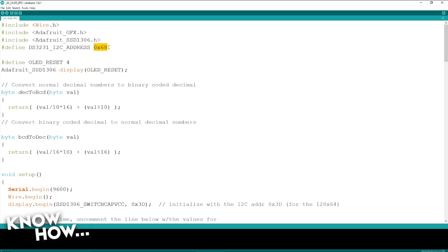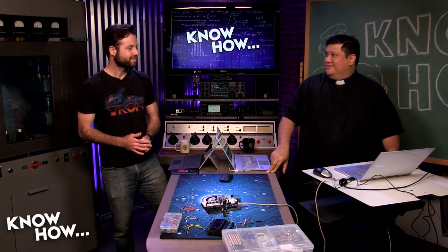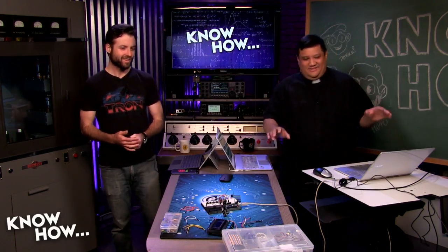Is there a limit to how many devices you can have? Yes, and it really is a hard limit based on the type of devices you install and how much wire you have. You kind of want to keep the wire short, because you're having to push that signal through that distance. Well, it's not so much the voltage, it's that the data becomes incomprehensible when you're pushing over 15 meters of wire. Just know that.